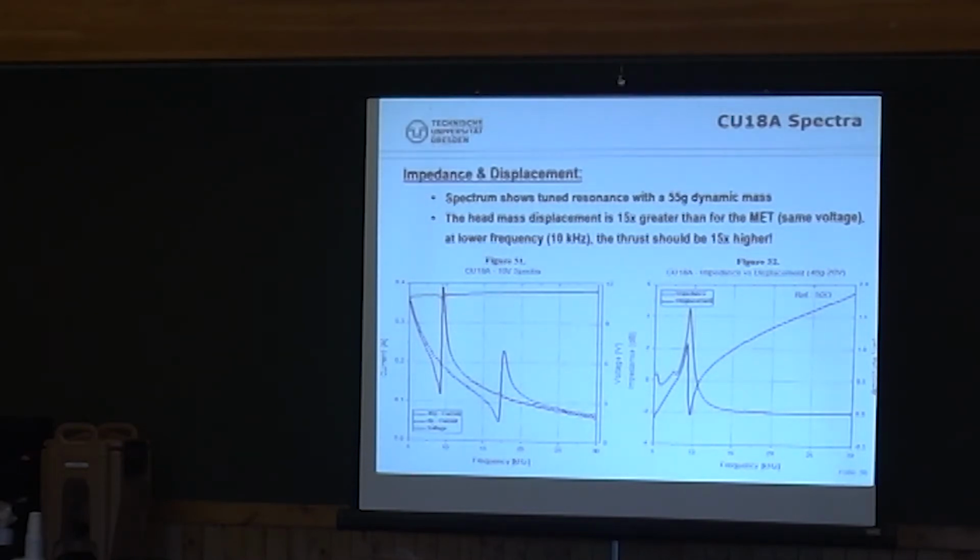This is not impedance, it's a current, sorry. So at resonance we expect a surge in current. This means that with a larger mass we can increase the power being supplied to the magnetostrictor. So that's what we selected, because then we can increase the amplitude, increase the power variation, and hopefully create a larger mass fluctuation.